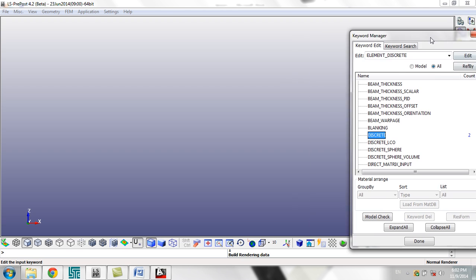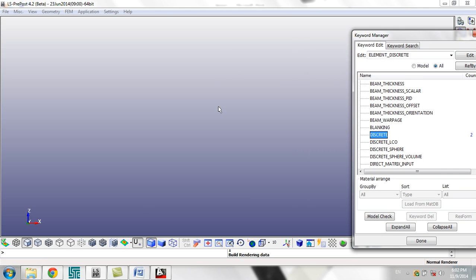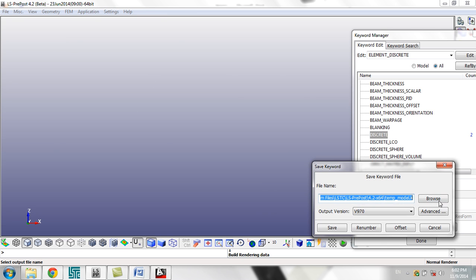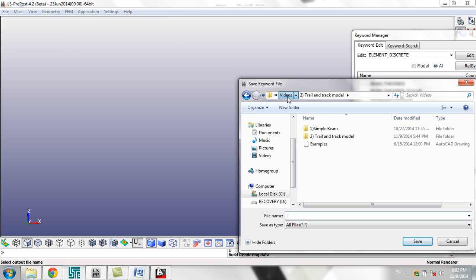And as you can see here, nothing exists in the view, right? Actually, this is an LS-DYNA problem, just a view problem. To solve this we have to save the file, close LS-DYNA, and open it again, and then you will see your model is ready. So that's what I will do right now. I'm going to save it, and this is my model.